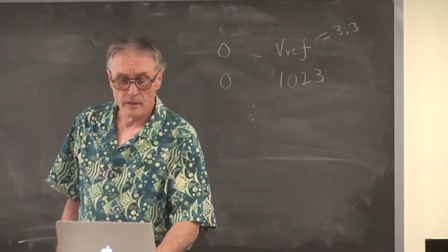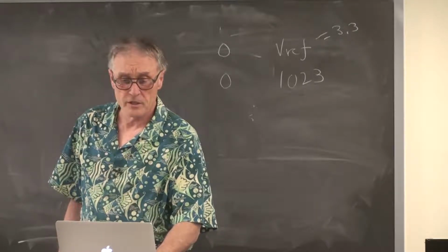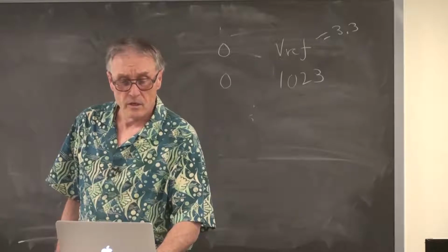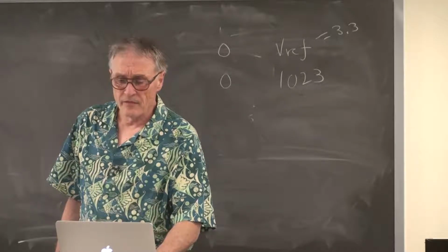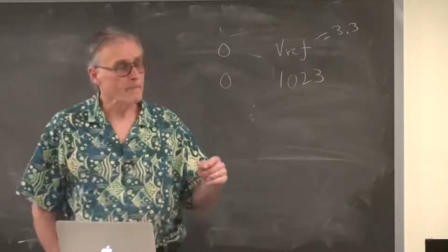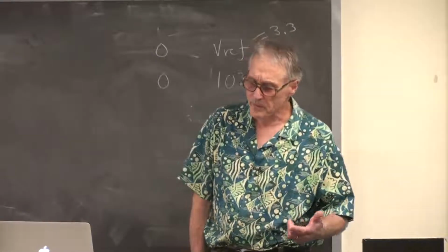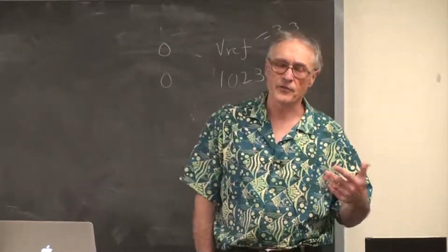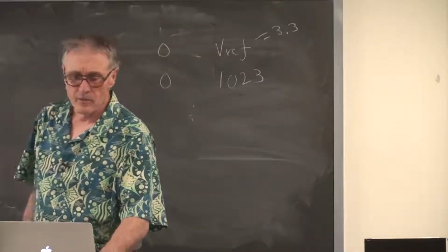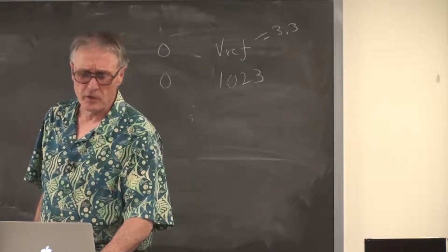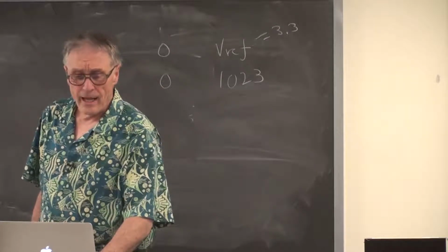So I wrote a little demo code here on the dev board page. There's an ADC example, which is a very simple example. I'm not turning on any ADC interrupts. I'm reading the ADC in a thread because I'm only reading it fast enough for human interaction.